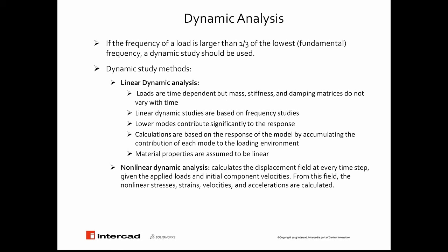Also, one very important fact: when we're talking about linear, this linearity considers the material. So if we have a nonlinear material and a dynamic loading, there is no other option than to move to nonlinear dynamic studies. We'll be calculating the displacement field, the primary unknown, at every time step with the applied load.